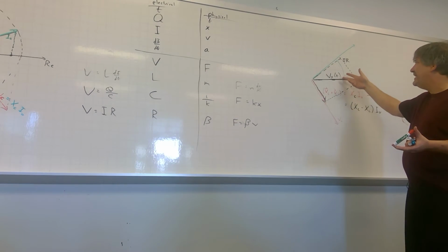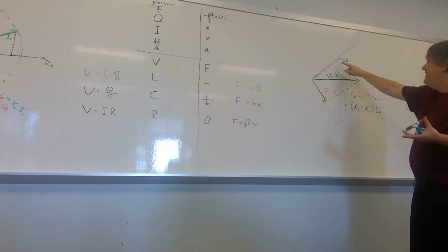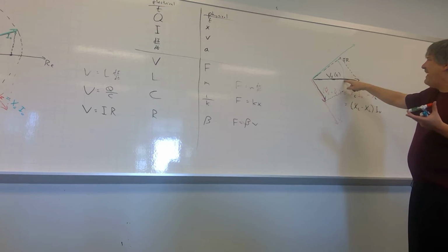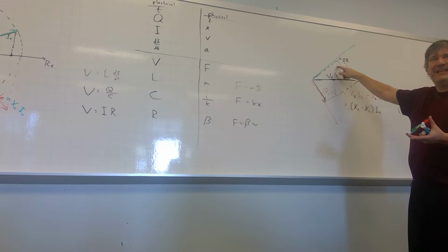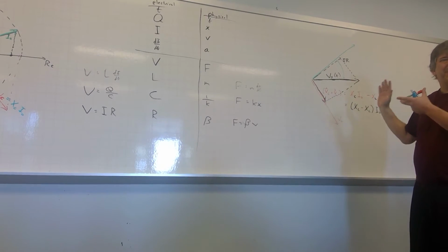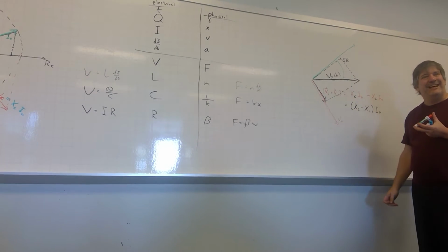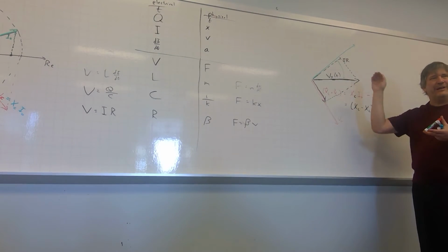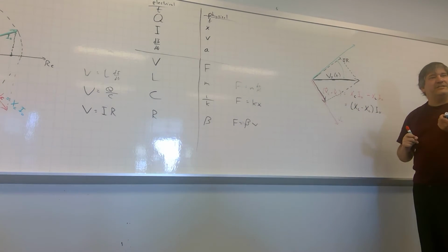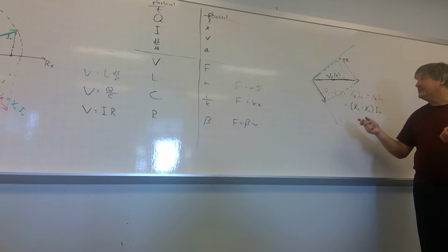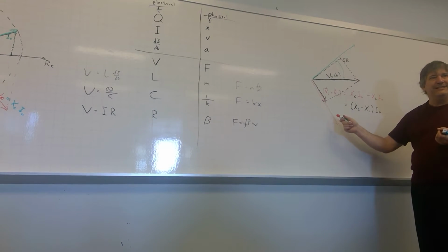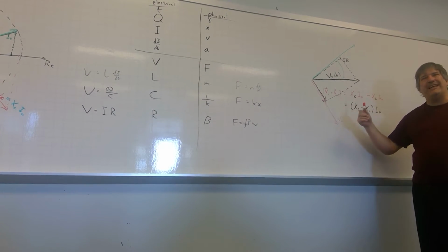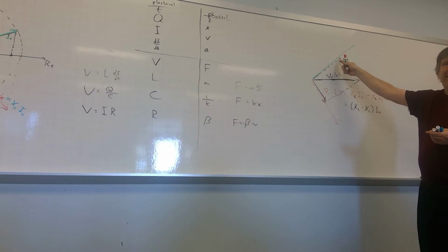In a capacitor dominated circuit, the voltage across the source doesn't lag a full quarter cycle behind the current like it would if there was only a capacitor in the circuit. But the voltage from the source does still lag behind the current, or the current does still lead the voltage. So a capacitive dominated circuit, a circuit where the capacitor has a higher impedance, acts a little bit like a capacitor and a little bit like a resistor.